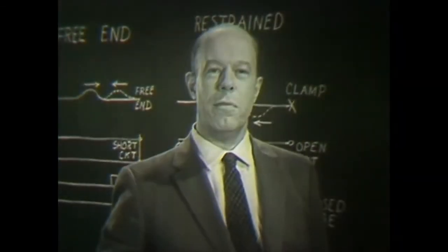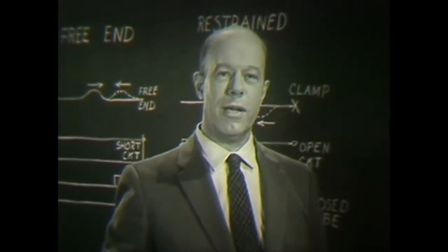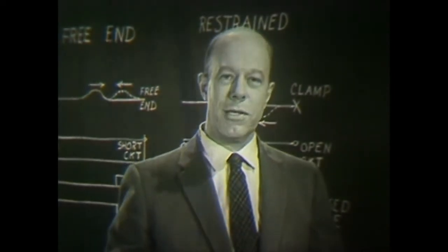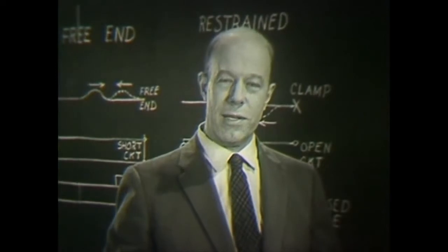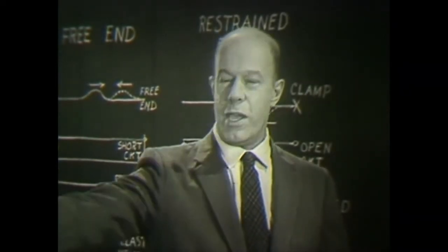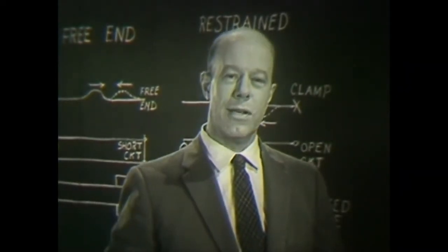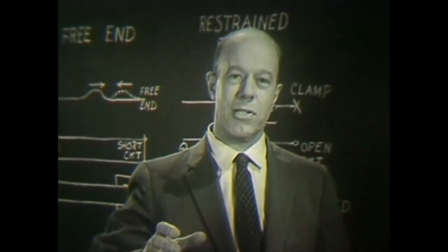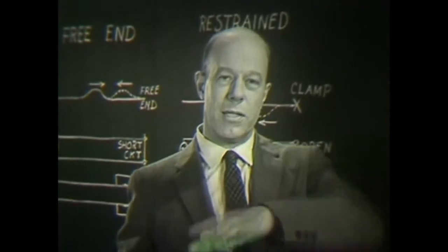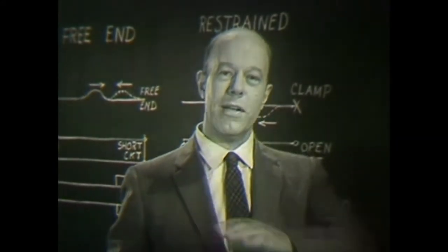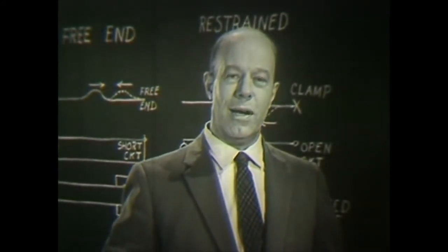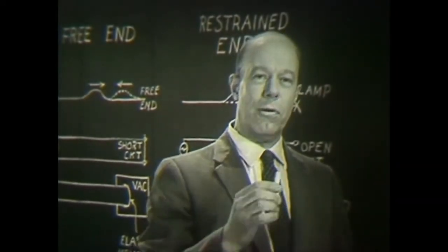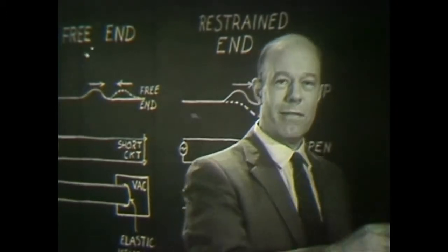You're probably most familiar with the term impedance through your studies in the field of electricity. But this impedance concept is just as applicable to wave systems of other kinds as well. On our mechanical wave machine there, for instance, the cause of the waves is the oscillating torque which I apply to the first cross arm, and the result is the oscillating angular velocity imparted to the medium. On that structure, then, the impedance, the mechanical impedance, is the ratio of the applied torque to the resulting angular velocity.